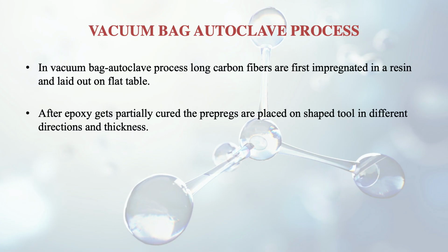After this epoxy gets partially cured, the pre-pregs are placed on shape tool in different directions and thickness. So according to our requirements, after this epoxy has been partially cured, this is placed on a shape tool to get different directional properties and thickness also.